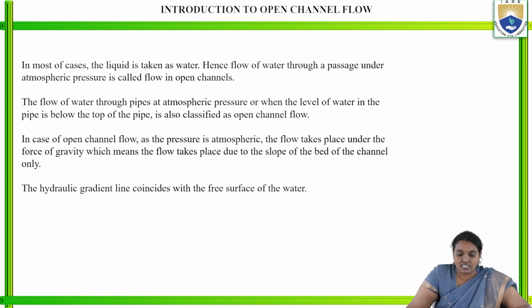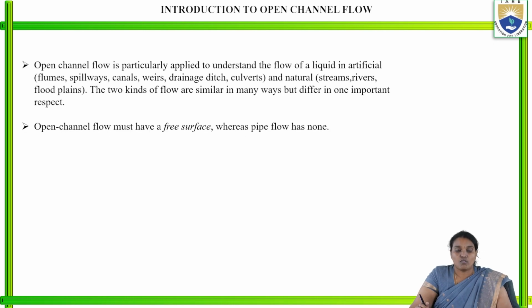In some of the cases, the pressure is atmospheric. The flow takes place under the force of gravity, which means the flow takes place due to the slope of the bed of the channel only. In this, one more important point, the hydraulic gradient line coincides with the free surface of the water. Open channel is particularly applied to understand the flow of a liquid in different types of